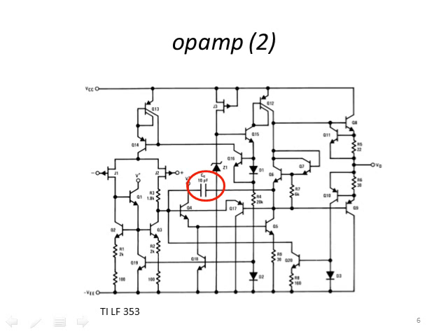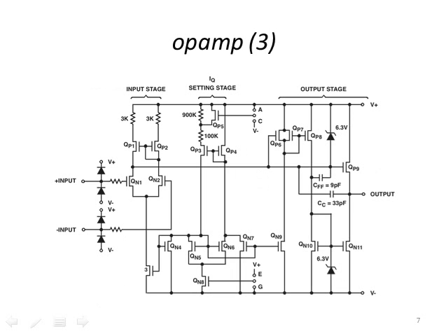We have all the same type of biasing elements. You'll see in the lower left part of the circuit we have our differential input with our JFET transistors. And then in the surrounding periphery you can see all of these current mirror structures that set up our bias currents. And on the output we basically have our amplifier and then our source follower to be able to source currents to drive particularly high current loads.